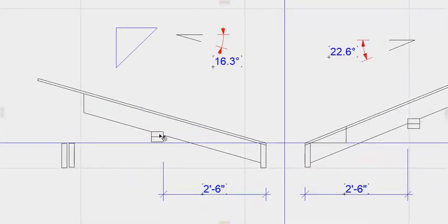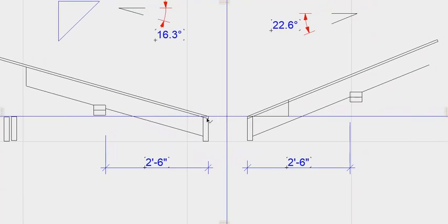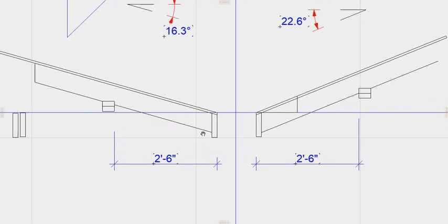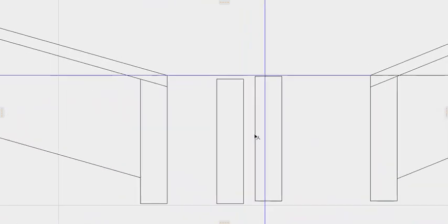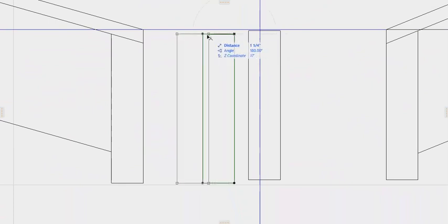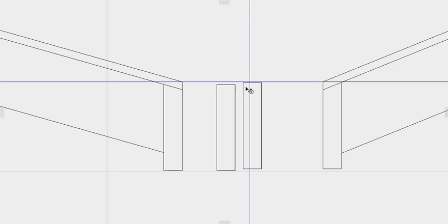You repeat the process on this side. You want to be 30 inches from there to there, and that sets up most of this. Now the other thing to keep in mind is the fascia, and I grabbed some little fascia boards here just as an example. So I'm using something that's 1.5 inches by 7.25. You use whatever you got.